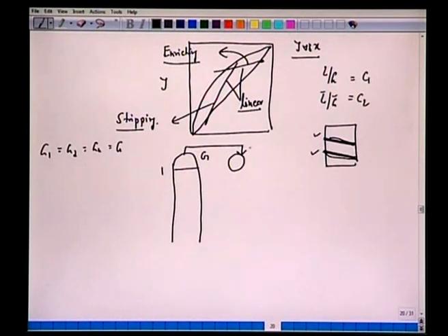So the molar flow rate of the vapor is G without any suffix. However, it has a mole fraction y1, because the mole fraction will change as the rectification goes on.